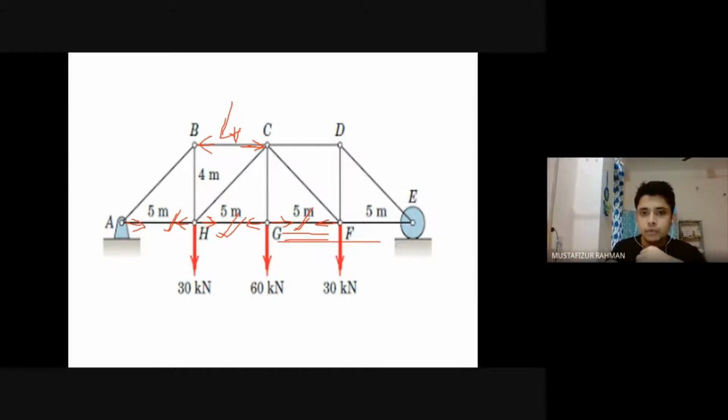So in the truss system, there will be no moment. There will be member force in the members of the truss, and this member force will be axial in direction. They may be tensile, they may be compressive, but the moment is not coming because the truss system is theoretically pin connected. These are pin joints, okay? So they cannot produce moments.